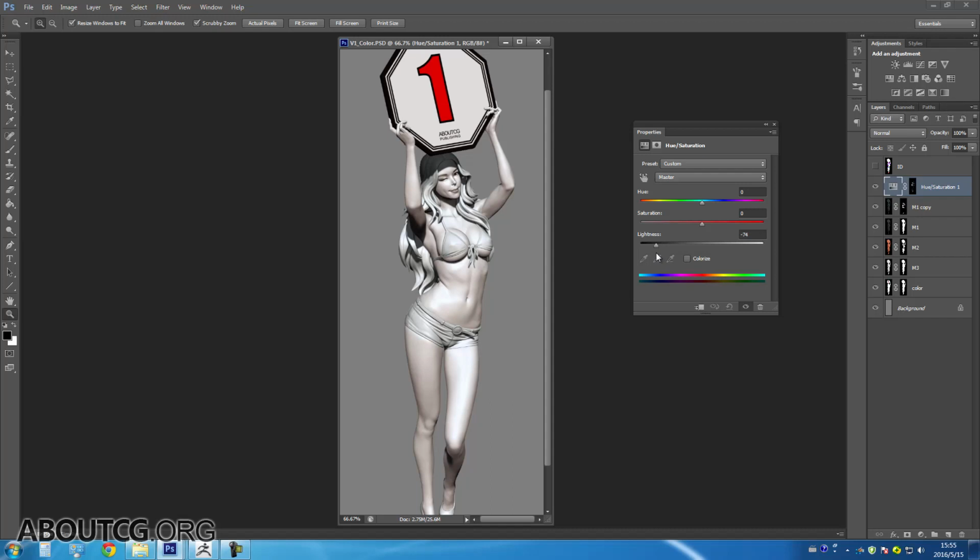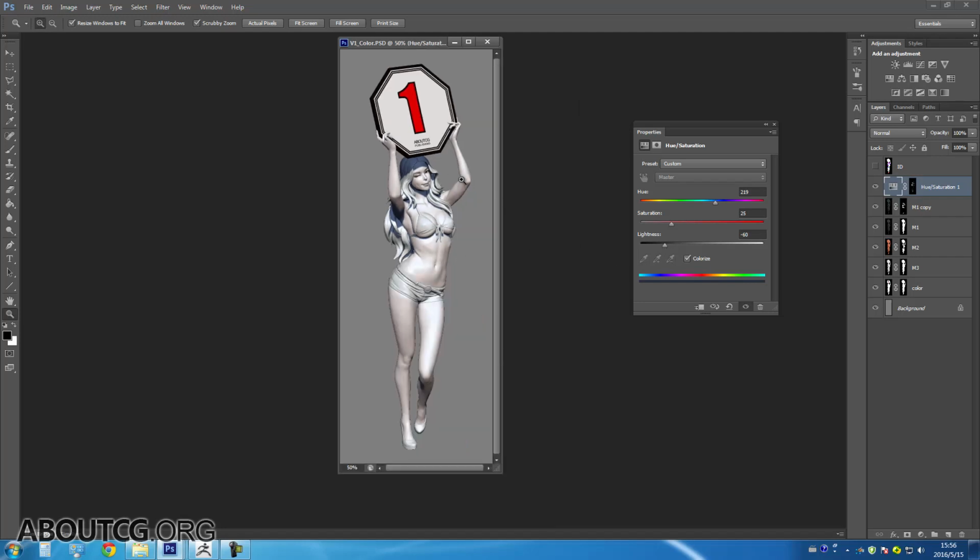Ctrl A, Ctrl C, Ctrl V. Then using the multiply blending mode, you can see that after adding the shadow, this image of the light source information has masked out all the unnecessary information using the shadow. So we can use this image by pressing Ctrl-Alt-Shift-E to merge all.